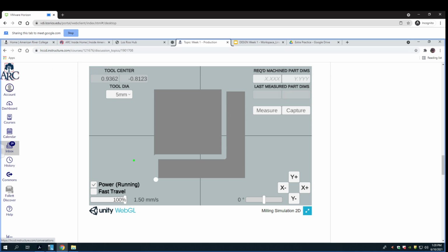Yeah, rounded, square. Certainly, you would most likely want it to not be sharp. You would want it to be deburred, dulled, rounded, a fillet. If you cut a little square off the corner, a little angle, it's called a chamfer.